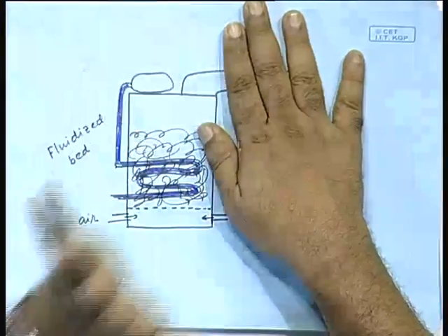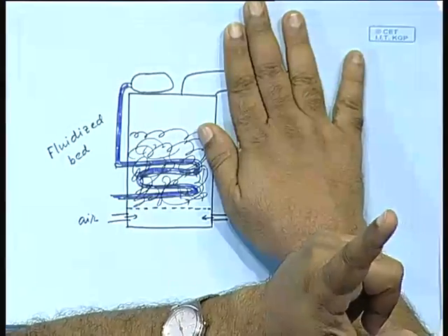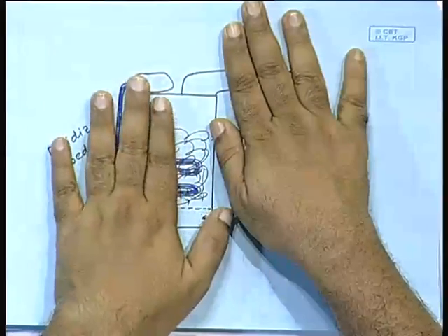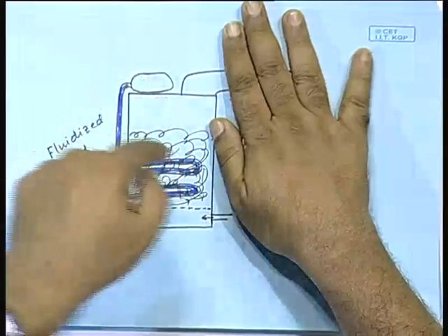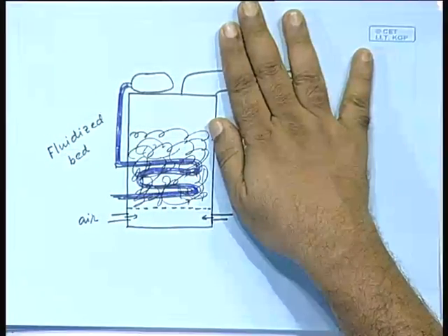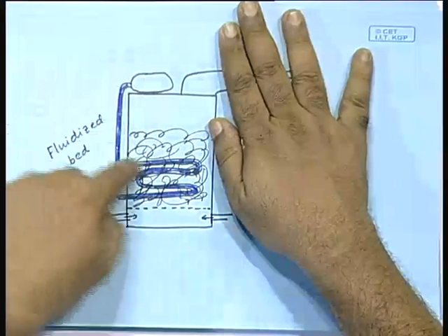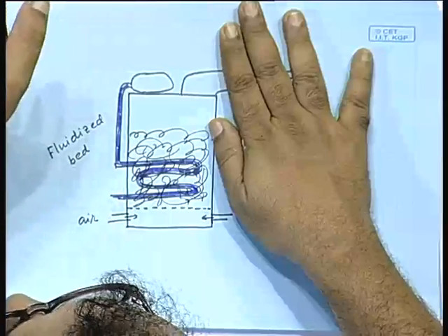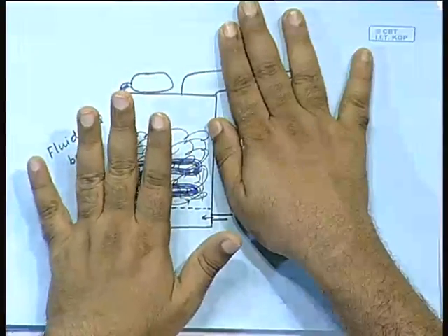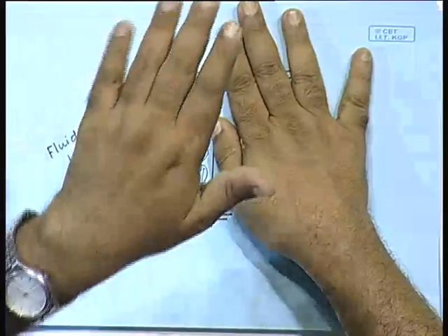In the third stage I said, don't mix them up. Third stage I said that now suppose we do not have the boiler here, rather the fluidized bed is used only for the production of a gaseous fuel, which means the boiler drum will not be here, the tubes will not be here. Here you will be using it only for the production of a gaseous fuel, and there the temperature will be maintained by means of putting a mixture of steam and air. Don't mix them up. Clear?